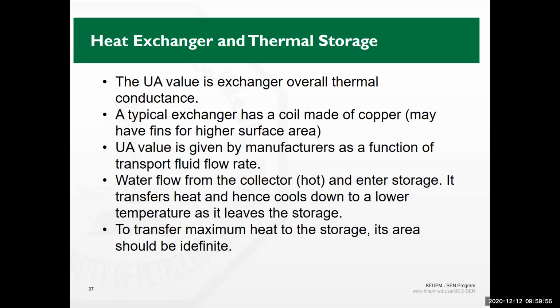If we are looking for higher heat transfer area and higher heat transfer between the heat transfer fluid and the storage medium, the UA value is given by the manufacturer as a function of the transport fluid rate, for a certain flow in kilograms per second or liters per minute. Then this is expected to be the UA value. The water from the collector, which is hot, enters the storage, heats it, and accordingly cools down to a lower temperature when it leaves the storage.